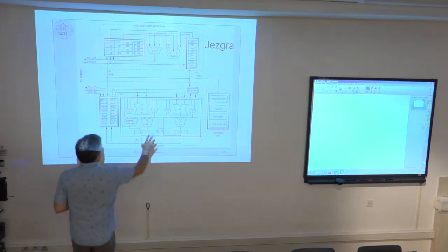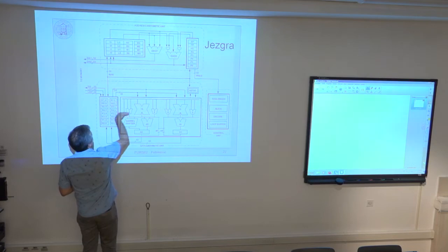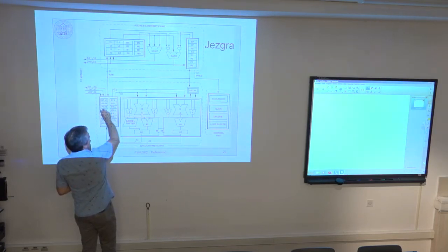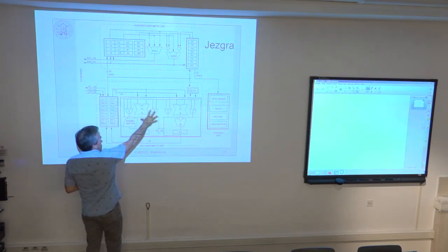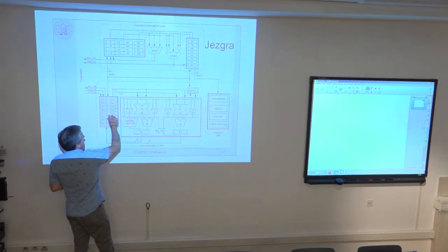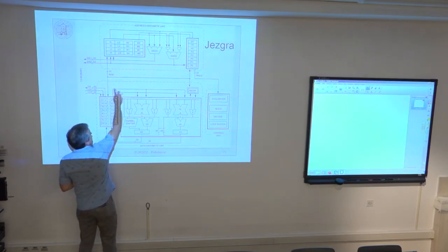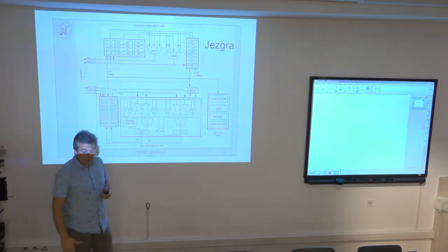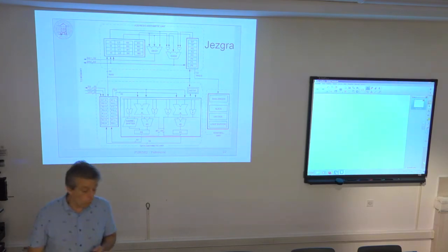In the instruction, I can select two such 32-bit registers as arguments for multipliers. For example, I can say I invoke R2 and R3, and I send them over these two buses. I have two 32-bit buses that are supplying the input arguments for both multipliers.